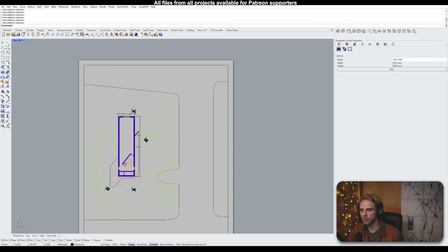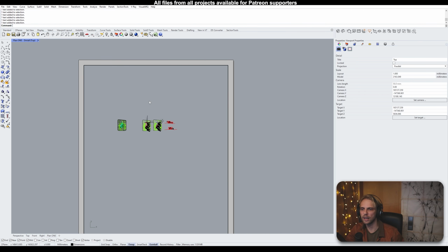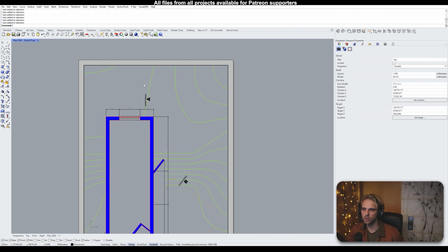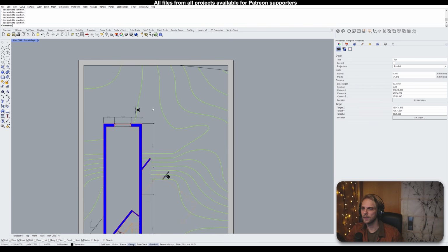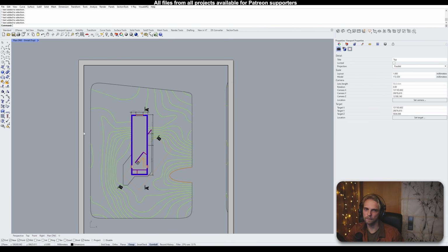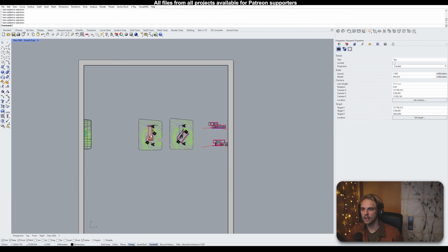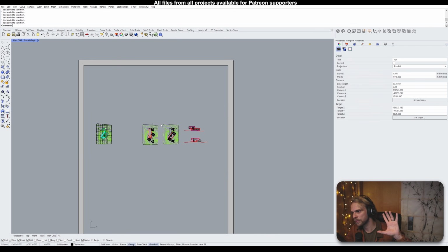They're a little bit bloated, and you'll notice that if I zoom out, they get even bigger. The more I zoom in, the smaller they get. And this is because of the adaptive scaling, right? As I'm zooming in, the scale of the drawing becomes bigger, while the text still retains the 1 to 100 scale that it originally has been set. So it will always try to retain the 6mm size on the page.